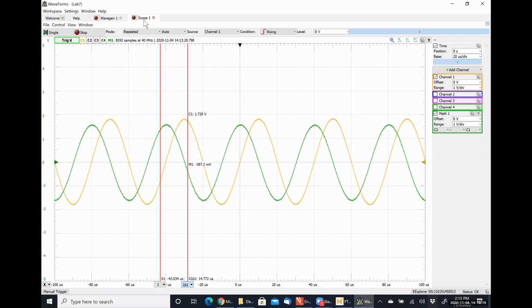From the graph, does the current, which is the green curve, lead or lag the voltage? So which occurs earlier in time? The green, which is the current. So for the capacitor circuit, the current is leading the voltage.